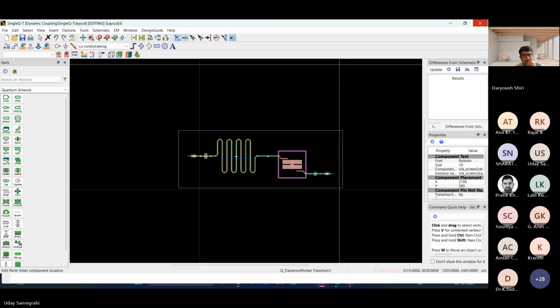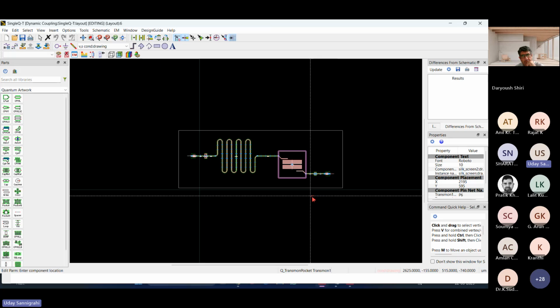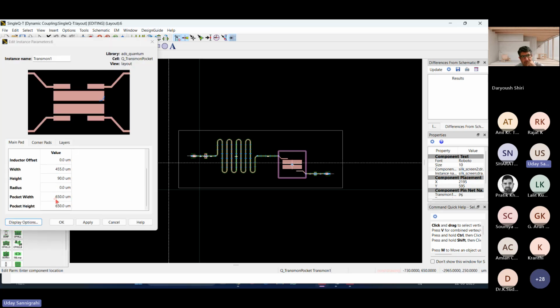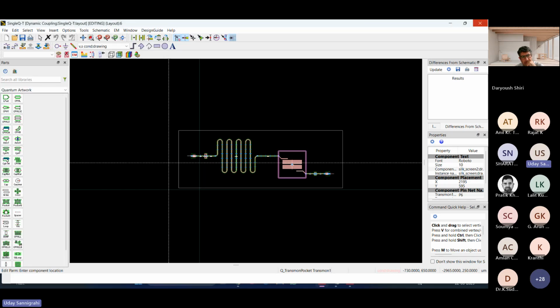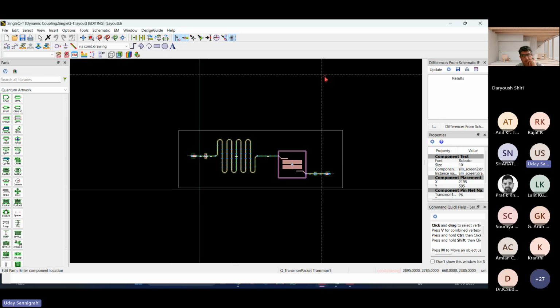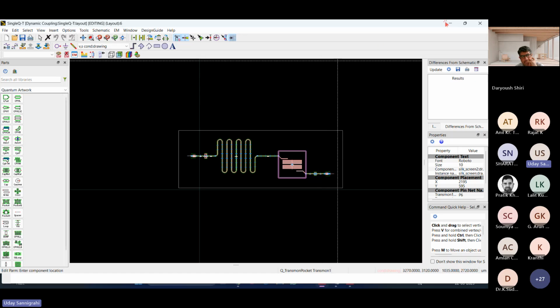This is complete. I have all the parameters, these transmon parameters I'm talking about, for my specific qubit. Now we're going to follow an architecture. Sarah has earlier shown a 4 qubit model where the coupling was done by the bus resonator. There are different coupling methods that we can use. Coupling is very crucial for a 2 qubit gate implementation, so we need to focus on the coupling architecture of qubits.